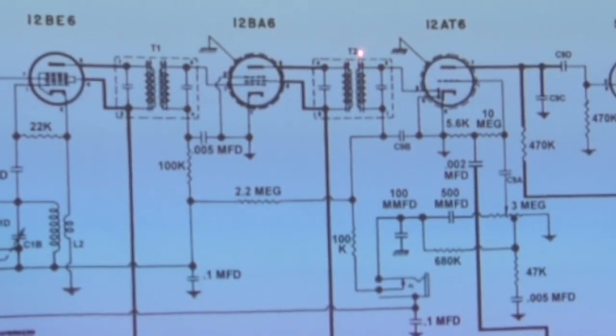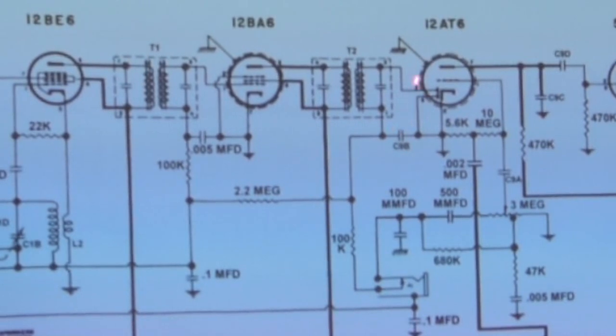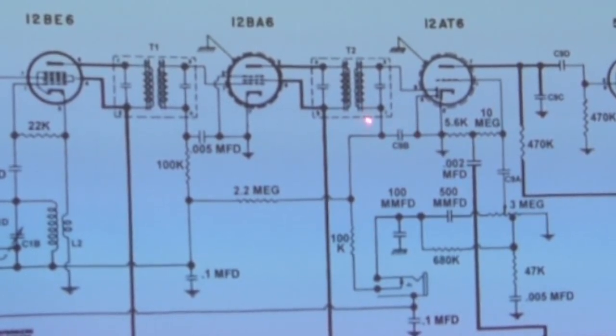Now, so let's say you do get a signal, and you're now going into the detector, and the detector is going to shunt the positive going portion of your modulated carrier coming in, which is at 455 kilohertz, of course. We saw that in the other slide. You're going to have a path of the demodulated signal coming down through the secondary into the RF decoupling or filtering capacitor here. Okay, so you get down here.